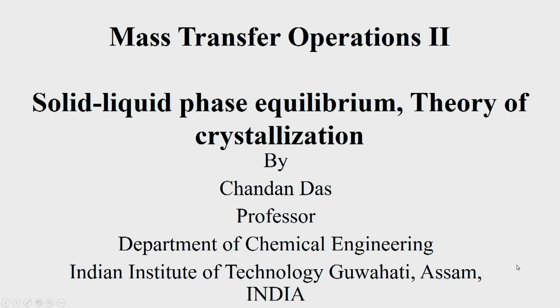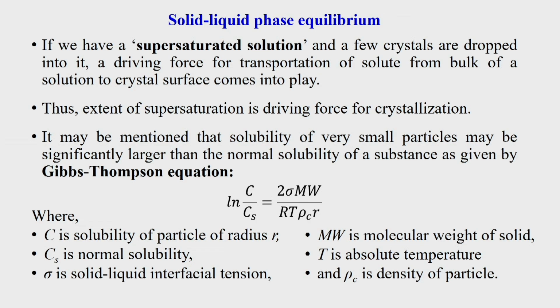Before entering into the solid-liquid phase equilibria, we should learn the terminology supersaturation. That is a quasi-static state of a solution where the capacity of the solute inside the solution is exceptionally higher than the regular solubility limit. If we have a supersaturated solution and a few crystals are dropped into it, a driving force for the transportation of the solute from the bulk of the solution to the crystal surface comes into play. Thus the extent of supersaturation is the driving force for crystallization.